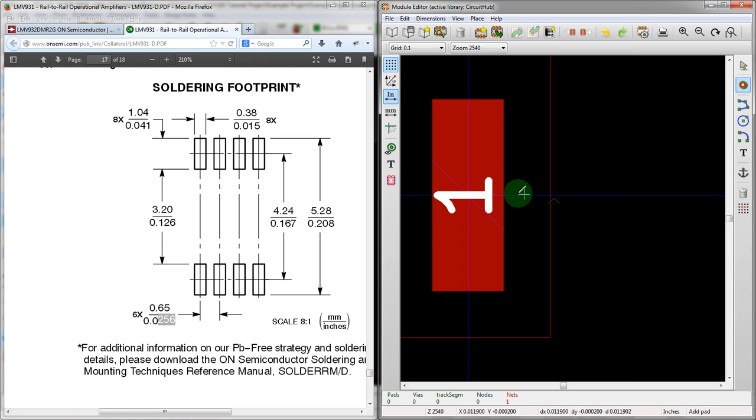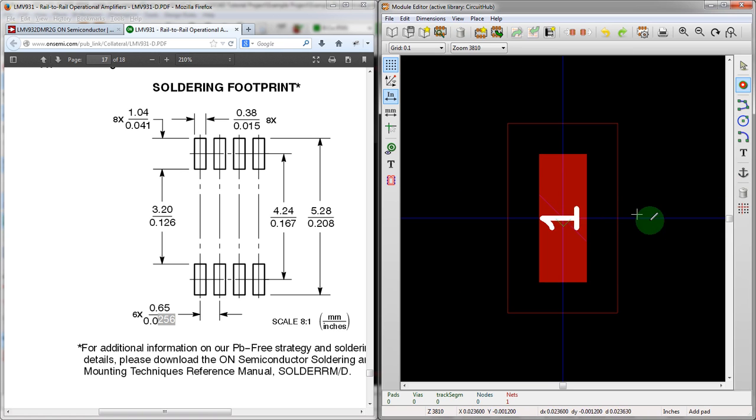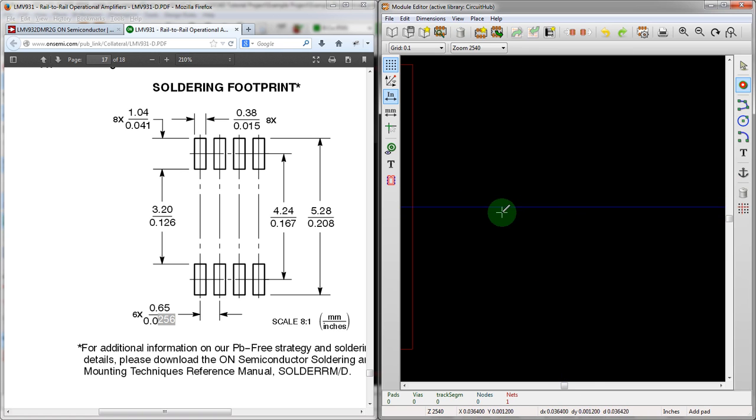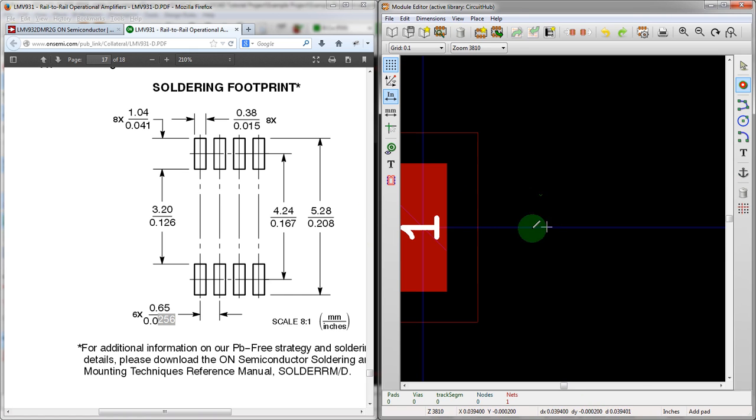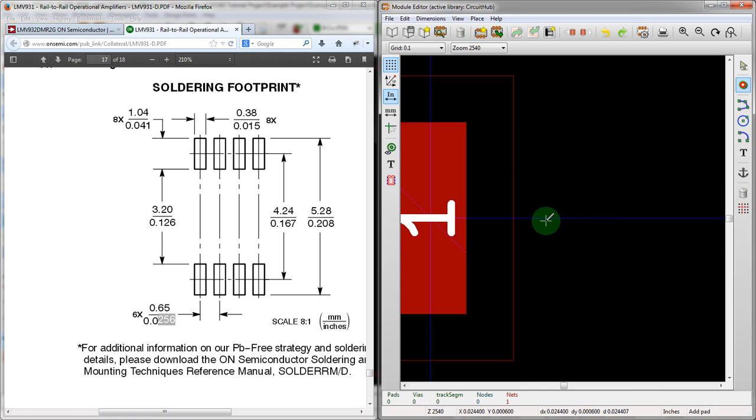Now, as you've watched in all the videos, grid is very, very important. You need to be careful about this. But since we placed the first pad right at 1,1, we can actually make sure that we move it over the proper amount. All right, so we're going to do a 25.6. The key here is to make sure 25.6 is on x, dy is at 0, and then this is the total distance. It resolves the hypotenuse of whatever triangulation you create there. So make sure that's right.